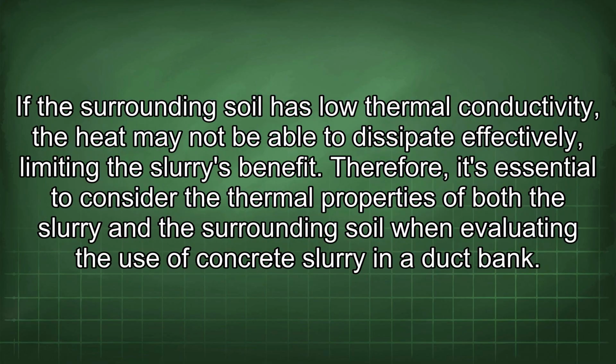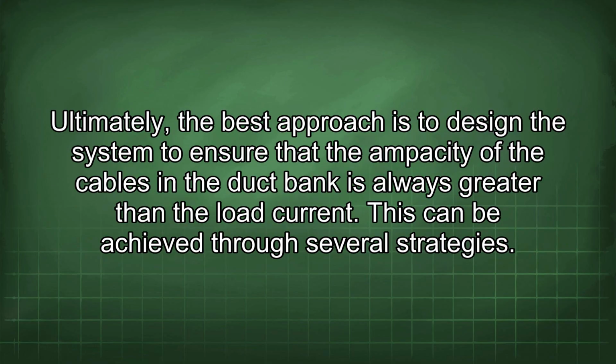bank. If the surrounding soil has low thermal conductivity, the heat may not be able to dissipate effectively, limiting the slurry's benefit. Therefore, it's essential to consider the thermal properties of both the slurry and the surrounding soil when evaluating the use of concrete slurry in a duct bank. Ultimately, the best approach is to design the system to ensure that the ampacity of the cables in the duct bank is always greater than the load current.